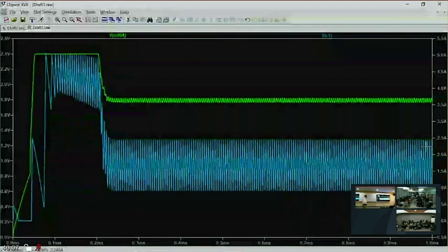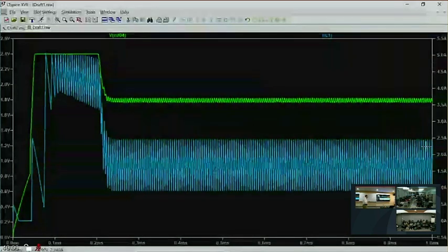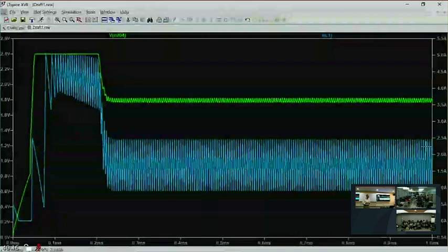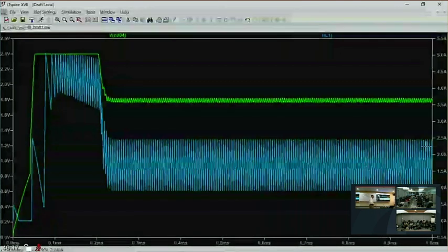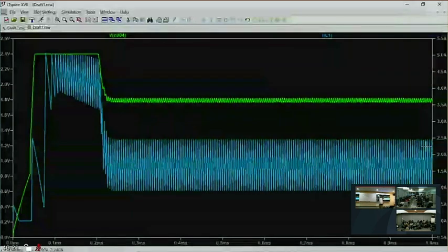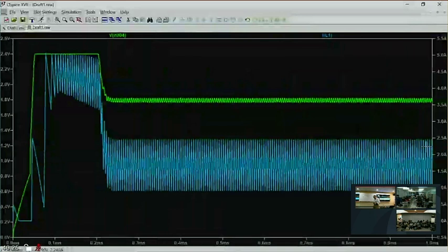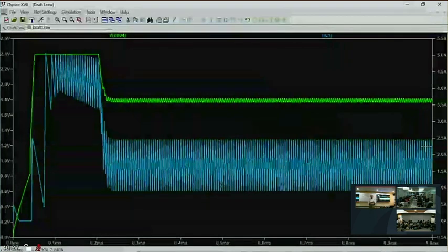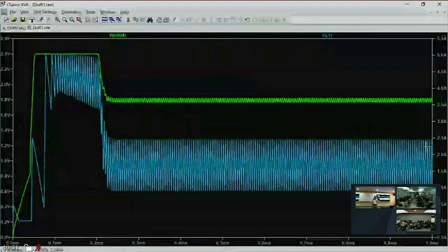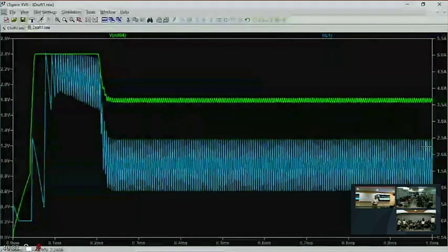The main problem with it is that in practice, the subharmonic oscillation is rich in stochastic noise, and that's a problem because of the nature of sidebands of FM modulation. See, FM modulated sidebands don't look anything like AM modulated sidebands. If you have a sine wave carrier and you modulate it AM with a sine wave, you have sidebands that are simply sum and difference frequencies from Euler relations.